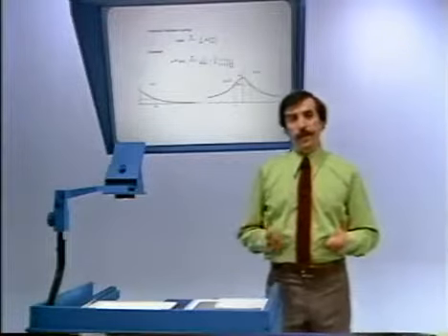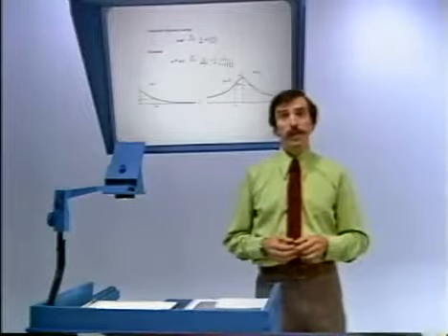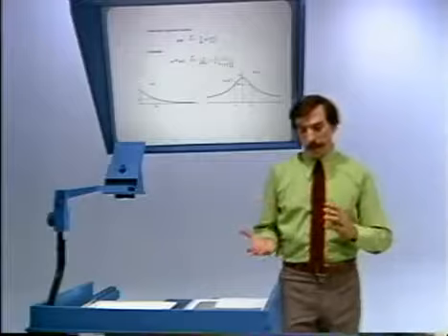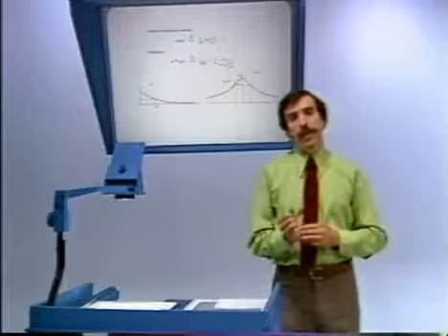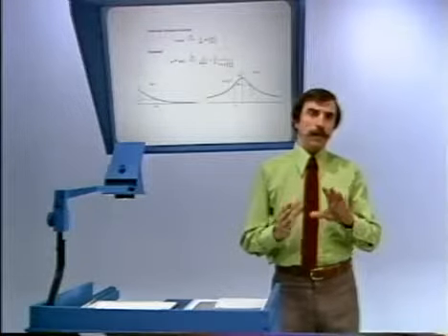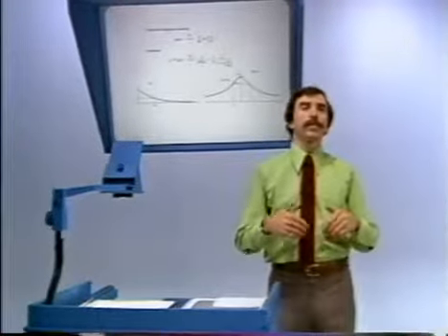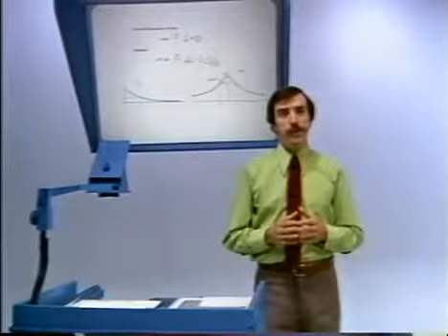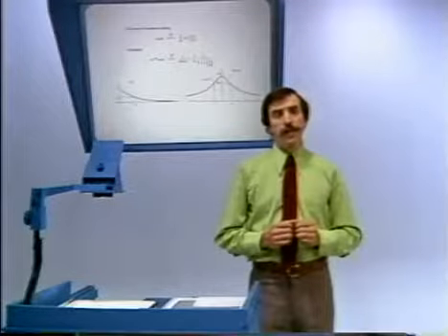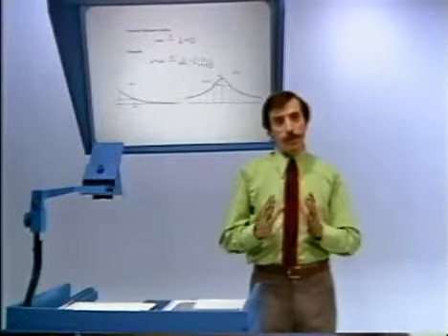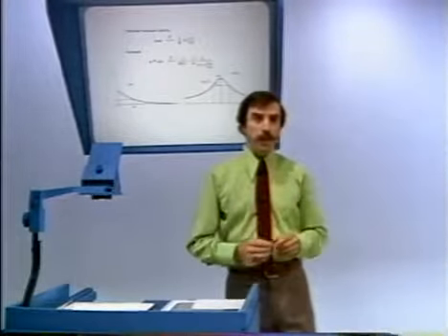Now, this, in fact, is probably a result that you're already possibly familiar with in somewhat of a different context. Essentially, you can think of this as a generalization of the notion that if I had a signal that was recorded on a tape player, and I played the tape back at, let's say, twice the speed, which means that I'm compressing the time axis linearly by a factor of 2, then in fact what happens is that the frequencies that we observe get pushed up by a factor of 2. And in fact, let me illustrate that.